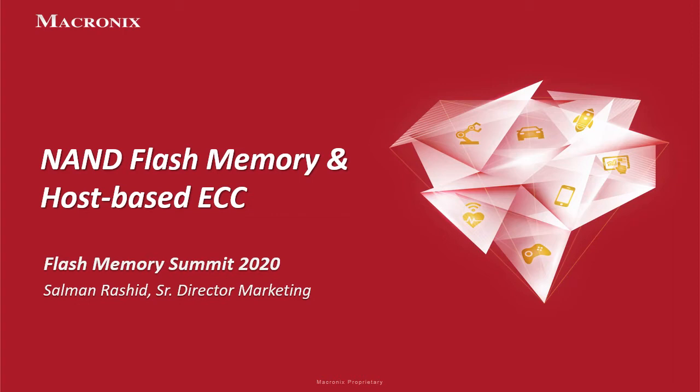Today, I will discuss how the serial interface, also known as SPI interface, in NOR flash memory has been widely used for many years, and why it is getting popular in NAND products as well. With serial NAND, system designers can switch from NOR to NAND using the same hardware, rather than completely redesigning their system for parallel NAND. As indicated by this cover slide, Micronix feels the future direction of applications that use serial NAND will eventually require the host to manage the ECC, not the flash memory, and this will be the main focus of my presentation.